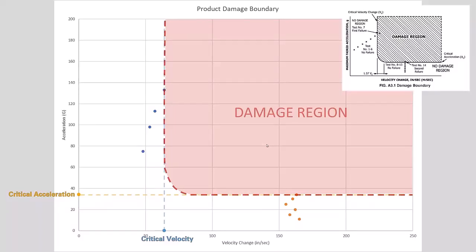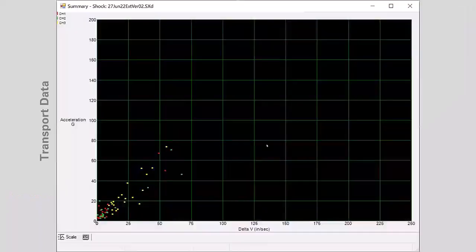Design me something with a system, whether that's foam, springs, depends on the size and configuration of the product. But if I have a 35 G fragility with that product, your job is to design a protective system that will never allow 35 Gs into my product. So you go find the right packaging materials, the right suspension system to mitigate or attenuate any type of shock from getting into my product at that amplitude. And another thing that I wanted to share here quickly is, like, this is now what I'm showing.